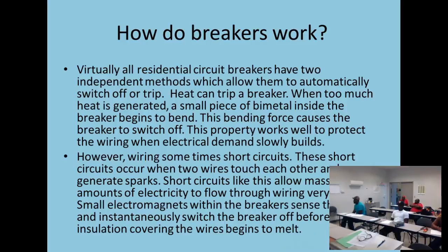Yeah, no, I just want to check the voltage. Once you cut it off, disconnect the load wires, then cut it back on and check for voltage again. If there's a dead short somewhere else, it's going to read voltage. If it doesn't, then the breaker's bad.